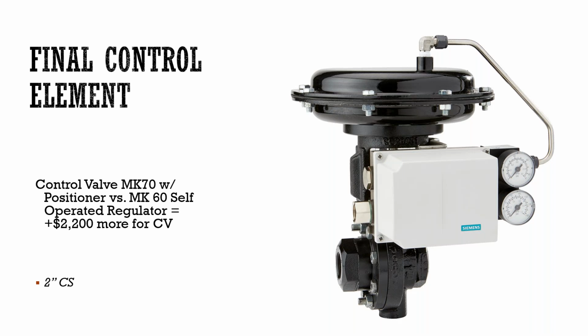Final control element, you can see here just a control valve. This is a 2-inch carbon steel control valve with a positioner, and we're going to look at the cost versus a self-operated regulator. And again, understand that we're going to have much greater accuracy in this control valve with a positioner than we're going to have in a self-operated control valve. But the valve itself is $2,200 more for the control valve than it is for the regulators.